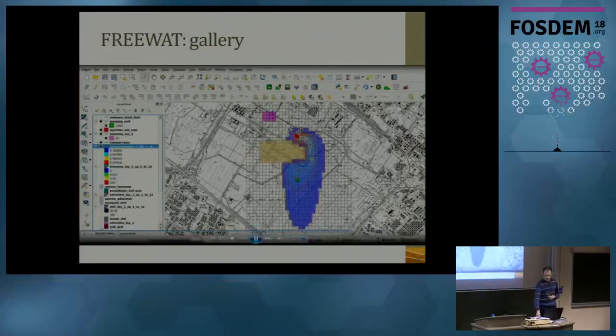Then one final thing I wanted to show about the modeling part is this one. So you see here the discretization of the domain, which is of course necessary for MODFLOW. And this is a heat transport model where you inject heat and you extract water here. And this is a lower permeability zone. And so you get the usual output, people familiar with MODFLOW know this, that you get from a MODFLOW file. So that's all possible here now in QGIS itself.